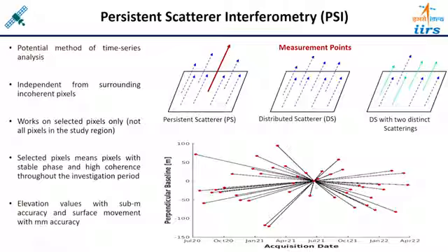And what is the perpendicular baseline? Here it is around 70, and here it is around 0. So the perpendicular baseline is around 70 meters, and the temporal gap is around 1 year. So this particular pair or interferogram is governed by a 1 year temporal gap and 70 meters of spatial gap.